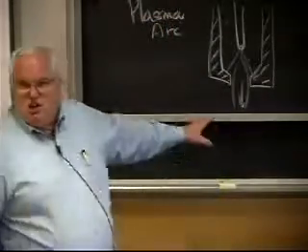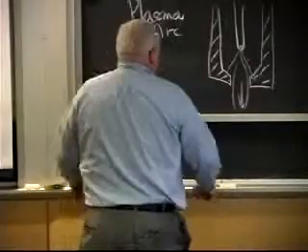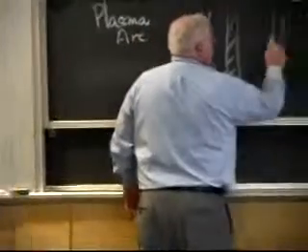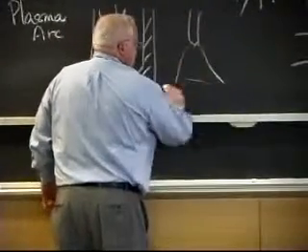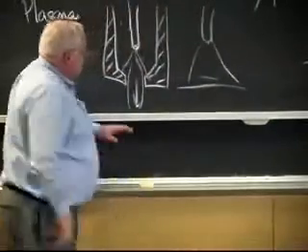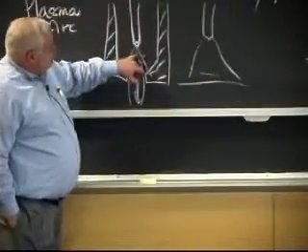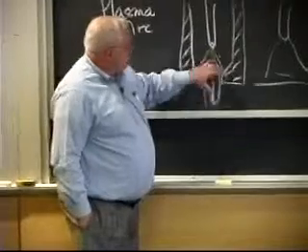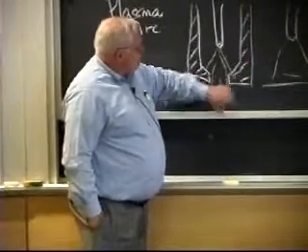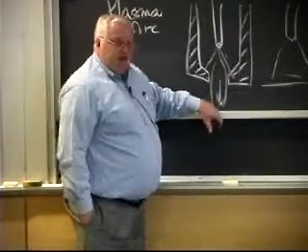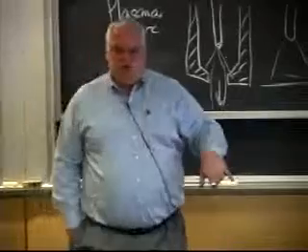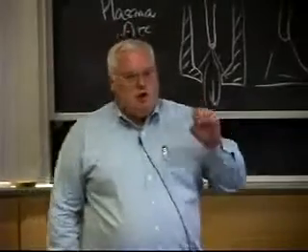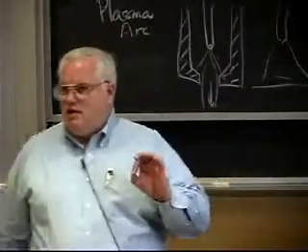And so you get a very, very stiff arc for a plasma arc. A gas tungsten arc with a tungsten electrode just sitting there in the air makes a nice bell shape as it expands and flows. If you do the same thing in a constant volume surrounded by this copper cup, and you let the arc shoot straight through, then you can get a very high velocity and a higher heat intensity.